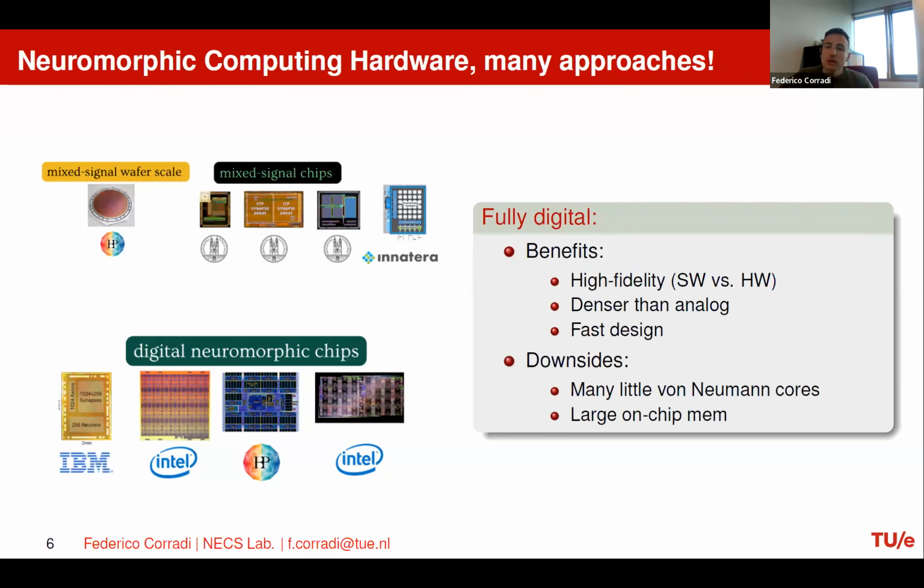And so the downside is that this type of processing system still has memory and computing elements next to each other. And typically each of these neuron cores is a little von Neumann machine that shuffles data between the memory and the processing element. Typically, you have time multiplexing of one processing neuron that processes 1,000 neurons by continually reading and writing the memory that is close to it.